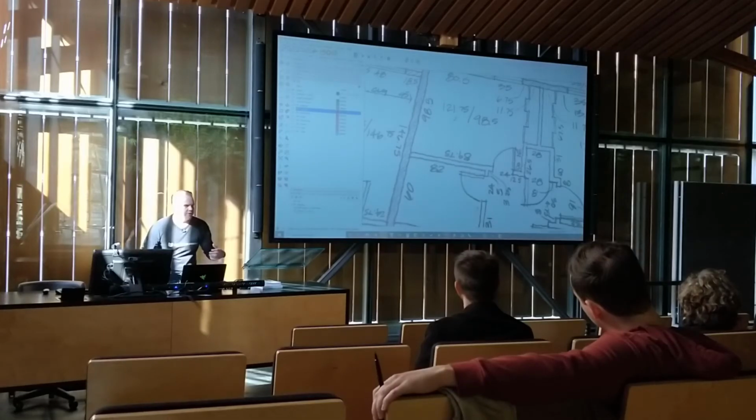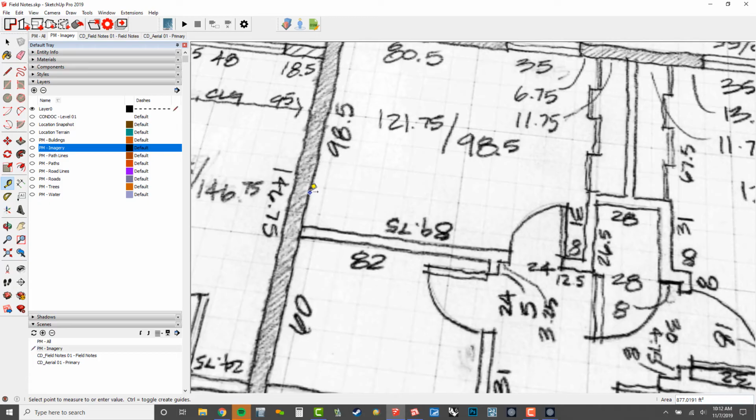I'm looking for a big dimension where I laid out the whole tape measure and got like 10 feet out of it. So I'll just measure from here to here, like that, and click. Let me do that one more time. All right, see at the bottom right corner, it's telling me that dimension is 6 feet, 3 1/4 inches. So I'm going to click to finish that measure command, and then I'm going to type 121.75 inches and hit enter.